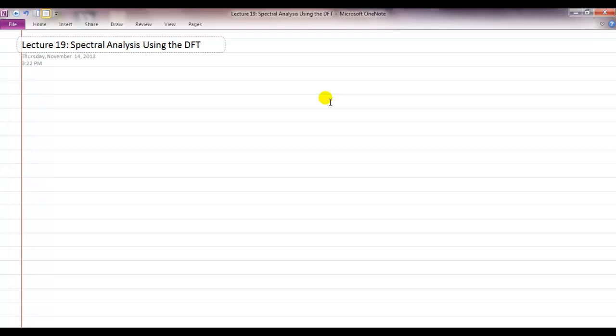There are, of course, many other applications of spectral analysis. You could be looking at a PCB circuit and trying to find out whether there is some spurious frequency, and for that you basically take your signal, sample it, do DFT analysis, and look at which frequencies are present or not. You could be interested in radar signal processing.